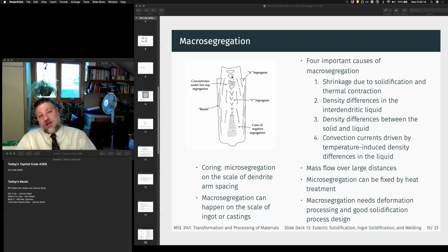And then the liquid moves around. So up here, these are big pores. These are like the cavity or central pipe. So essentially this ingot is designed to be chopped off here. This is also a bottom fill ingot to stop entrained gases and things like that from coming in. So most of the time with large ingots, they will be bottom fill.